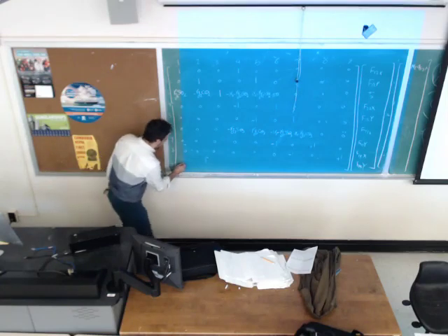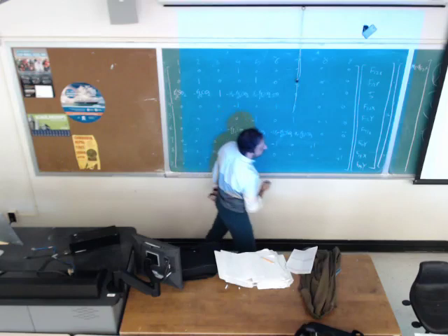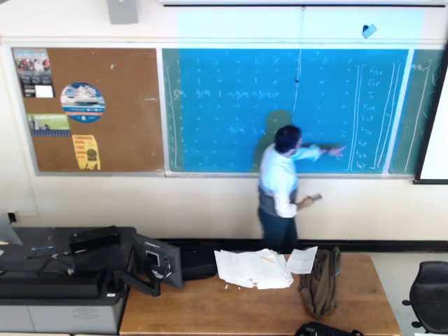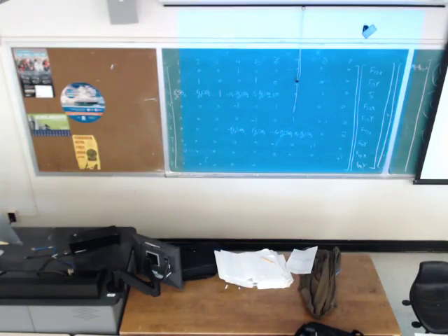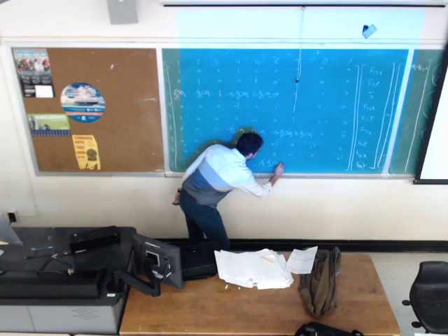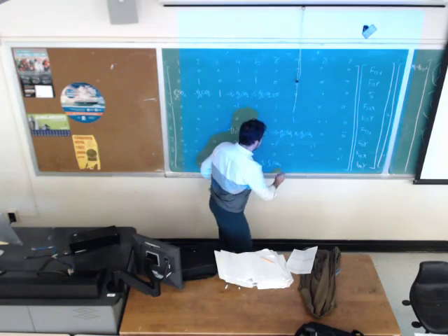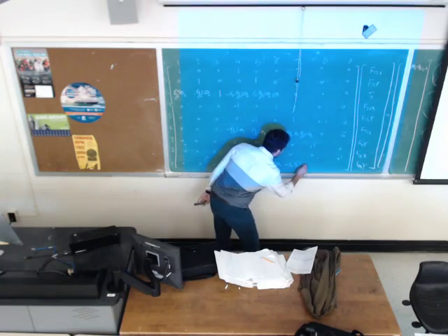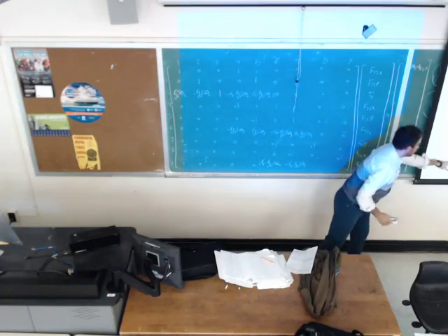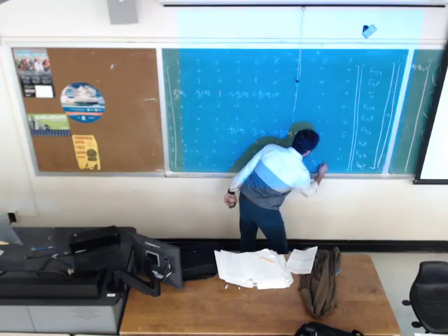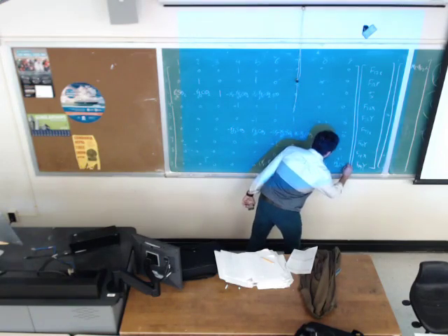And last equation. F1, we have F34, 1, 2, 3, 4, from here. F43, here we have F34. I put a negative behind that, negative times negative positive. It's going to be R4 minus RG4 sine of theta 4. This guy is going to be negative R4 minus RG4 cosine of theta 4. Coefficient of F14 is positive RG4 sine of theta 4, and last term is positive RG4 cosine of theta 4.